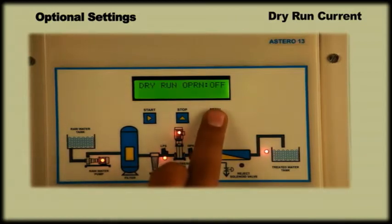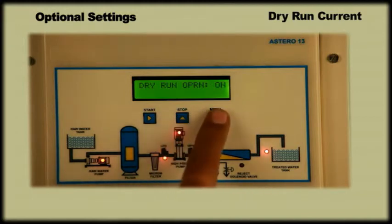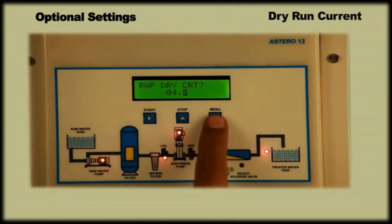On pressing the Menu key again, the display will show dry run operation off by default. In order to turn it on, use the Stop key and press Menu. Now the display will ask for the raw water pump dry current value. This set point has to be between normal current and dry running current. For example, if the dry running current is 3 ampere and normal current is 6 ampere, then one can set it to 4.5 ampere and press Menu to save. Similarly, the high pressure pump dry run current value can be set. Press the Menu key to save.